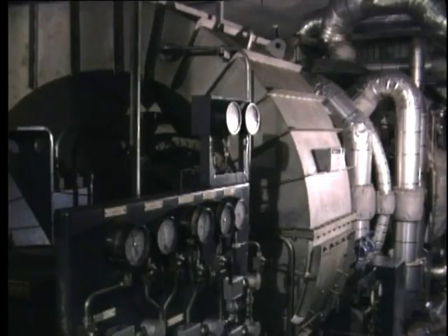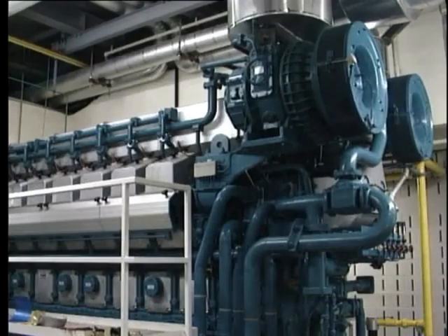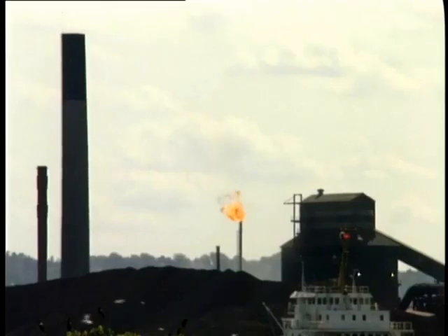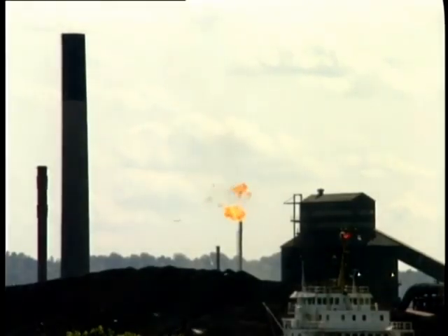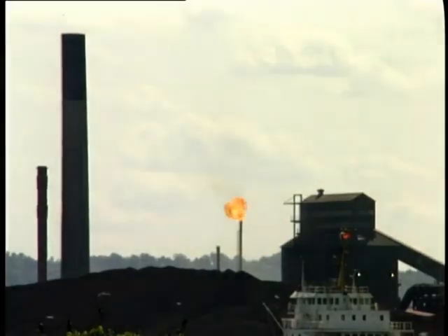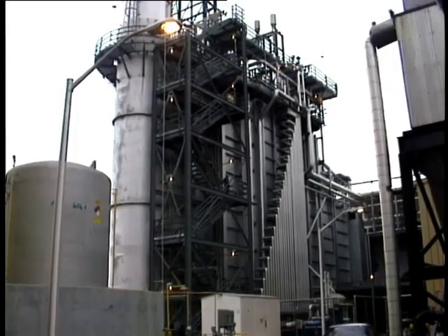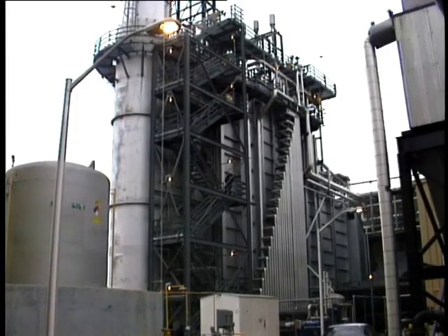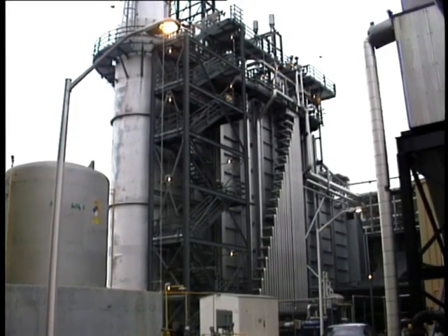Up to now, we've been considering that our boiler obtains heat by the combustion of fuel. But in many applications, particularly where cogeneration is involved, the heat is provided by high-temperature waste gas. This may come from several possible sources, such as the exhaust from a gas turbine, the exhaust from a diesel engine, or waste gas, commonly known as off-gas, from an industrial process. The heat from this gas can be usefully employed to produce steam by passing it through a heat recovery boiler.